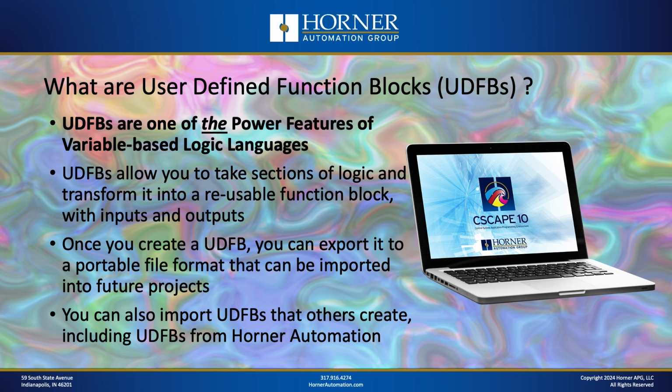So what are user-defined function blocks? Well, user-defined function blocks are one of the power features of variable-based logic languages, and really one of the primary reasons we spend so much time on those languages on this channel. UDFBs allow you to take sections of your logic and transform it into a reusable function block with inputs and outputs, just like a regular function block in Cscape.